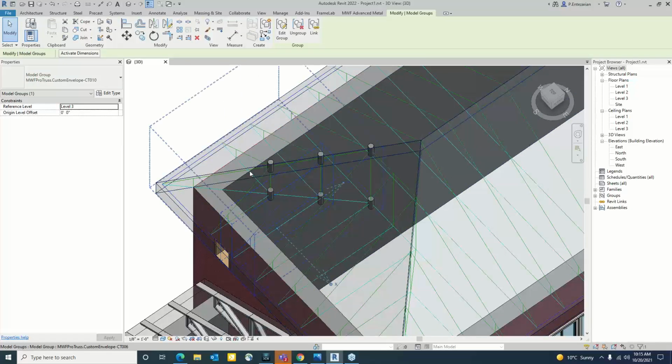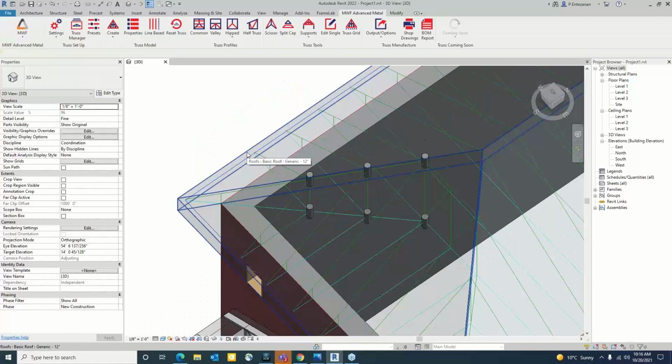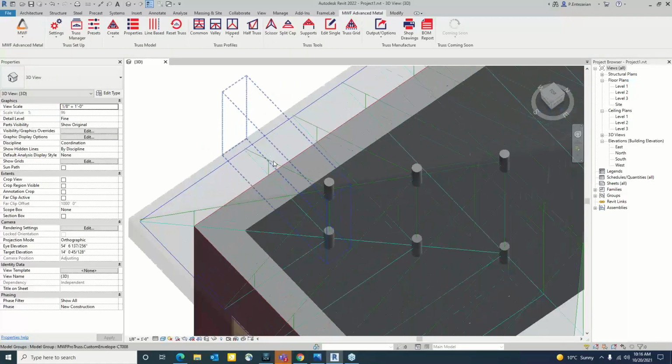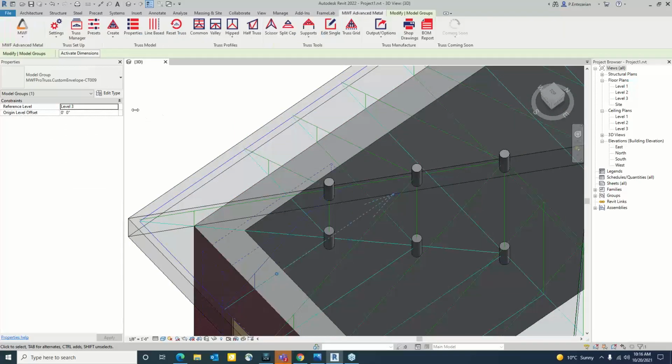And then we can design the wedge, then the other jack, then the other jacks and wedges from the other side of the roof. And the last step would be designing the hip, because we need all this information for the hip to get designed. Now that we have added all these truss connections, let's select one of the jacks and click on Create.